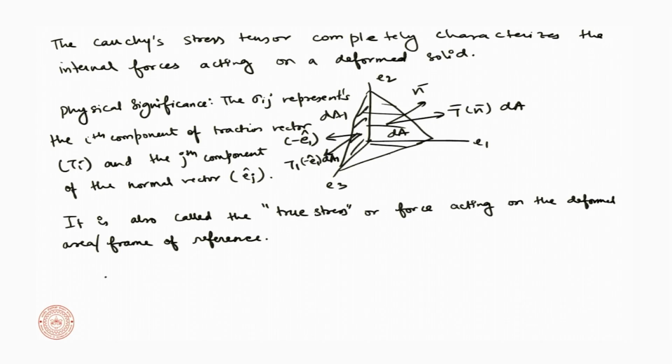Okay, one thing to point out in this case that I maybe should have done earlier is that the Cauchy stress tensor, if we just go back a few steps, is symmetric in nature. So I might flip sigma ji with sigma ij. Please be aware that it is done with the consideration that the Cauchy stress tensor is symmetric. So this transpose gives us the same tensor as an output. Okay.